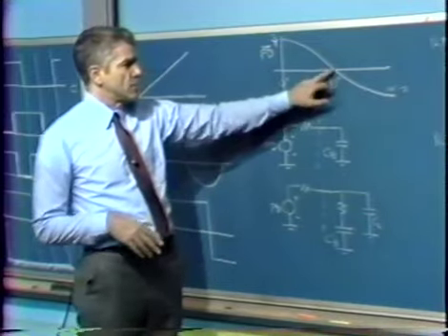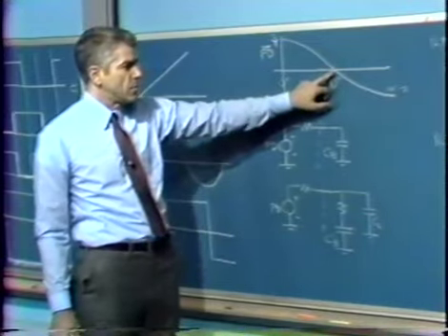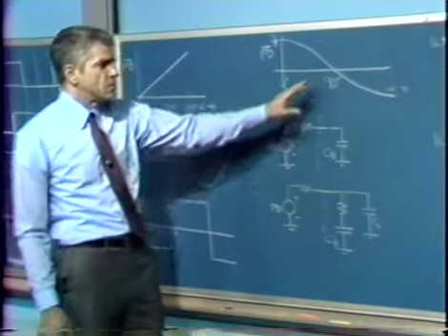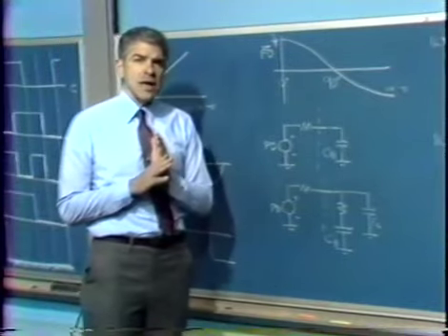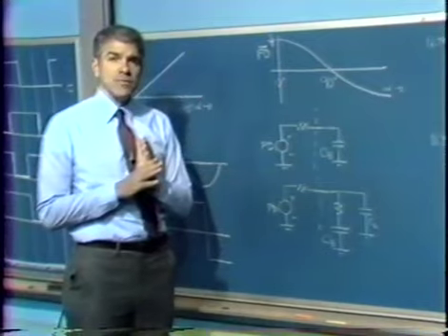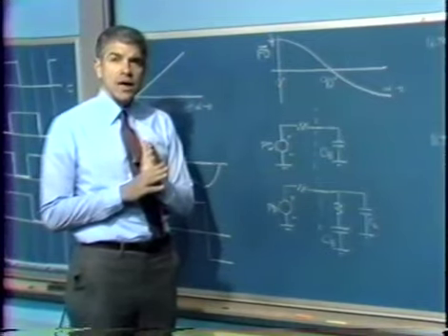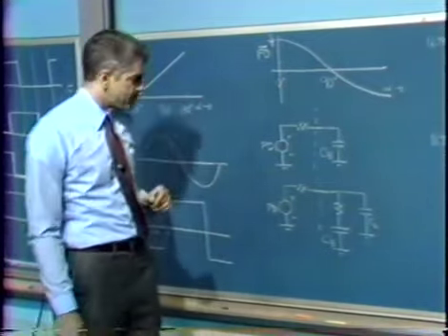In some of these detectors, for example, the operating points are 90 degrees apart. In some, it's 180 degrees apart. But if we included an additional integration, when the input frequency were constant, we drive to that equilibrium point exactly. This 565 doesn't include that.